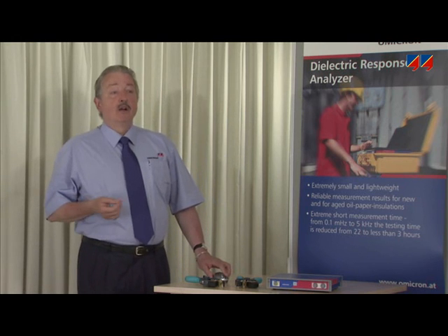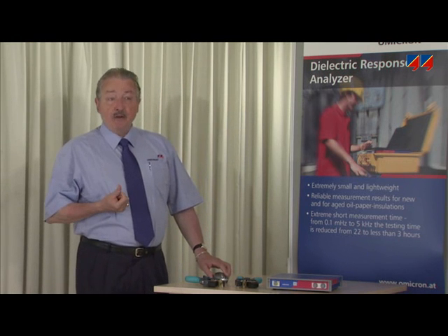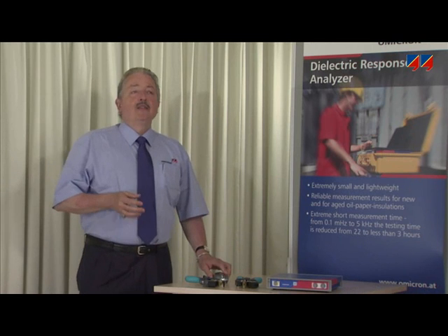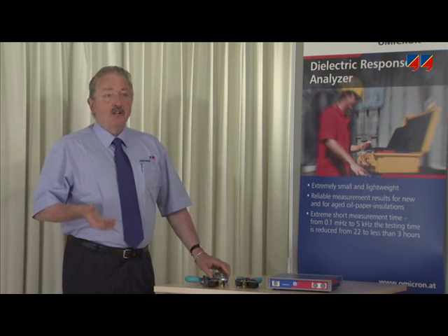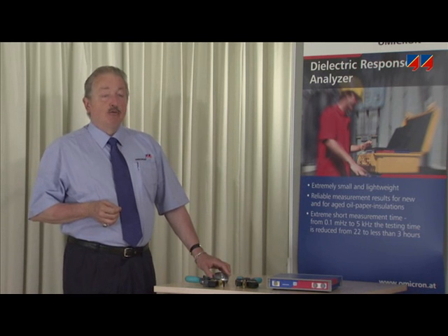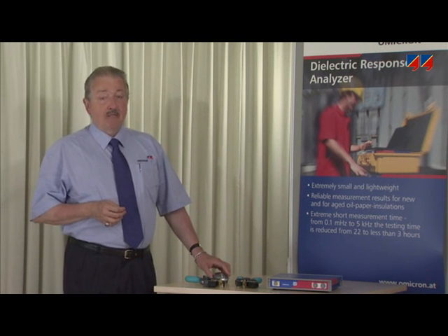Differences will also appear when comparing different dielectric response methods to each other. For example, one customer may utilize the Dirana to test his transformer in the first instance, then later may measure the water content using a competitor's product. Both instruments will give different values for water content. In this case, once again, the explanation must be that there are differences even under laboratory conditions, and because of this, there will be differences for dielectric response methods as well.